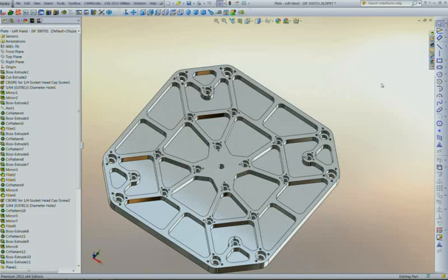Well, that's true, but oftentimes in those shops they're machining similar features over and over. They might be doing a lot of pocketing or a lot of roughing or a lot of drilling, that sort of thing. Any feature that you do more than once, even if it's of a different size, you can store inside the knowledge base in CAMWorks, and it'll be programmed automatically the next time it comes up. So it can be a big time saver.